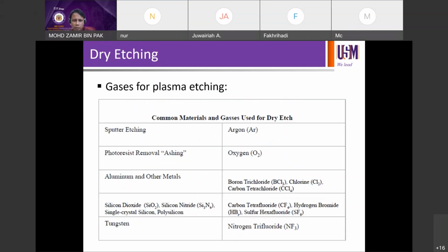Right, typical gases for plasma etch. We typically use argon, okay, for an isotropic process. Okay, argon. Then anisotropic. So for resist removal, etching, remember, etching is isotropic because you want to remove blanket. You want to remove all. Whereas earlier with anisotropic we wanted to dig only certain areas, we wanted to etch certain areas. But this one is like blanket removal.